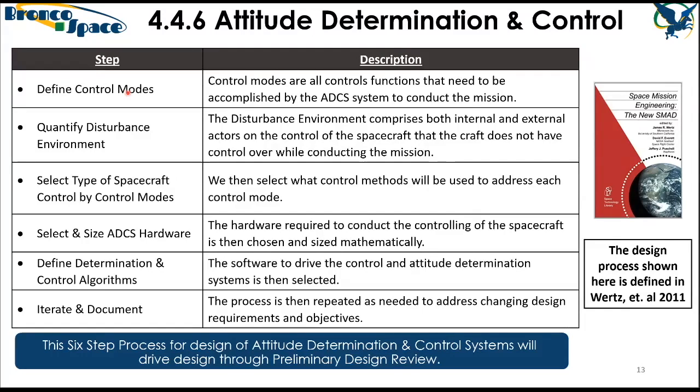Another control mode that's really popular in spacecraft is a sun pointing mode, because it's very uncommon for CubeSats to have articulating solar panels. Moving parts and reliability don't really go with the whole low cost paradigm. Let's say one face of your satellite has a lot of surface area with solar cells on it. You might want a control mode where the spacecraft makes sure that face with all the solar cells is pointed perpendicular to the sun to get maximum power generation.